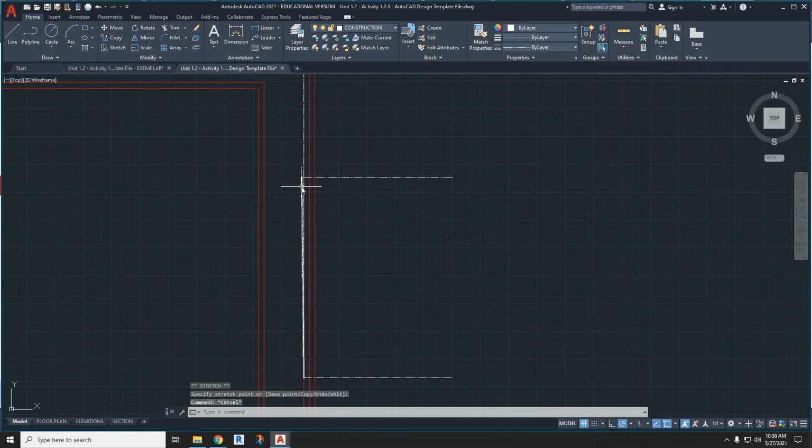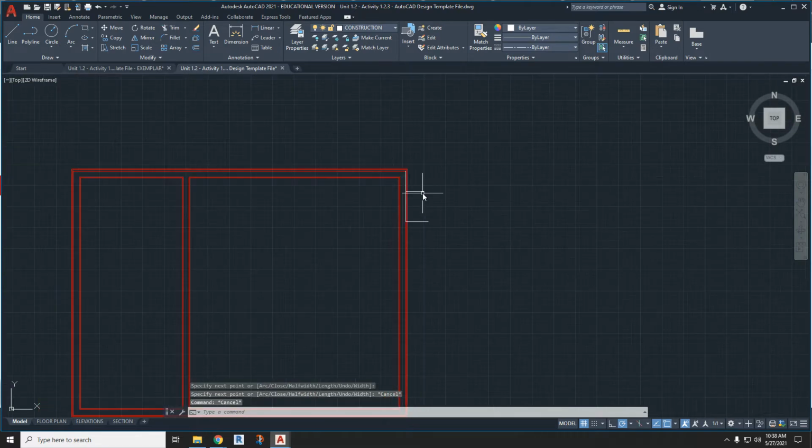That didn't work out well at all. Let's redo that. Let's do a polyline, PL, that connects the lines. Multiple lines get connected together. So 1 foot 6 inches, 1.5 feet. All right, now that's going to be the edge of that door.